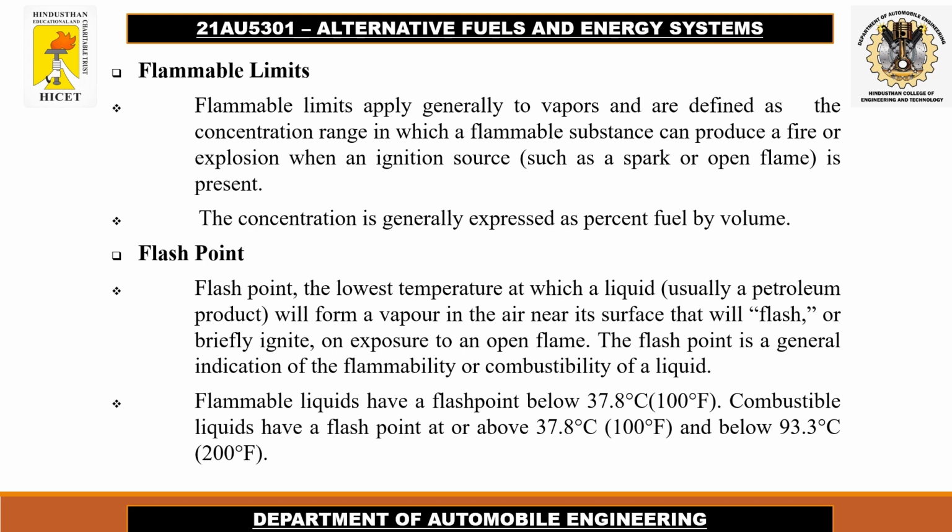Next important point is flash point. The flash point is the lowest temperature at which a liquid, usually a petroleum product, will form a vapor in the air near its surface that will flash or briefly ignite on exposure to an open flame. The flash point is a general indication of the flammability or combustibility of a fuel.